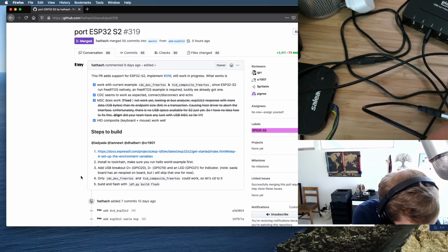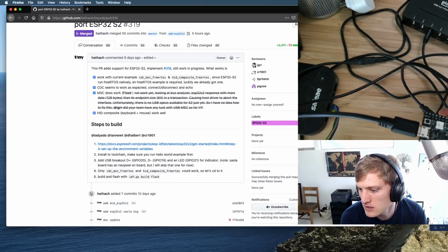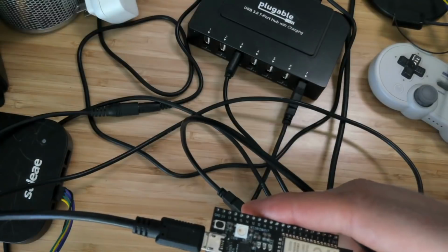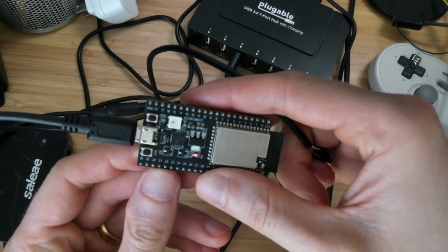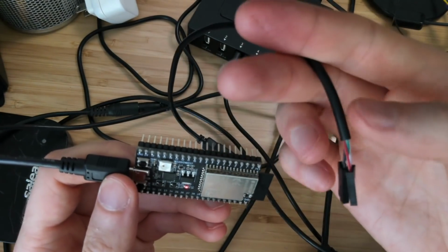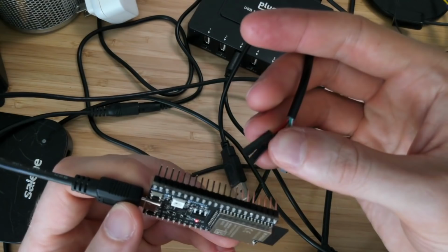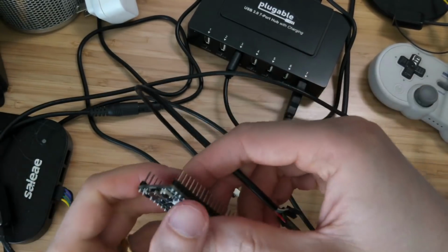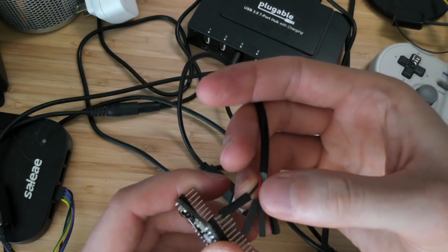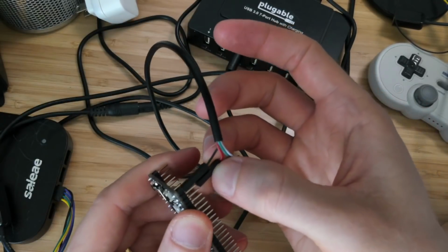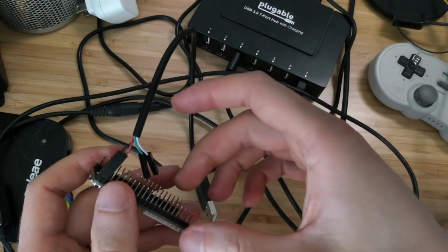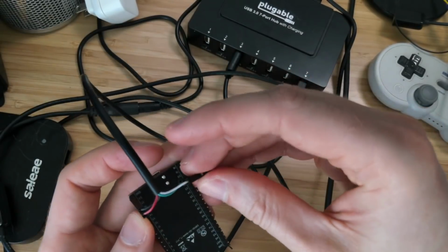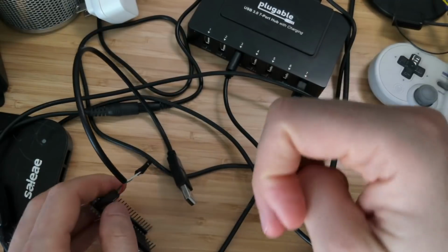So on here, I'll switch to the overhead and you can sanity check my wiring. Okay, so here's the chip. I'm gonna try powering it. I assume, actually I don't know the color coding. I assume black is ground. Actually, let me unplug this. Black is ground. Red is 5 volts. And then which white and green are D plus and minus? And I don't know if it's going to reach. It's going to be awfully close. But I don't actually know which one is which.